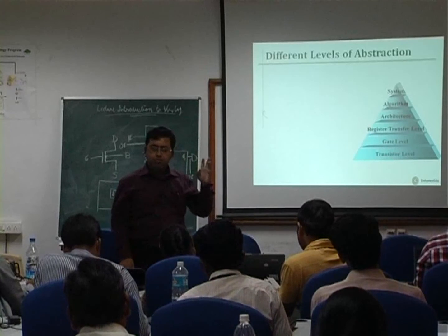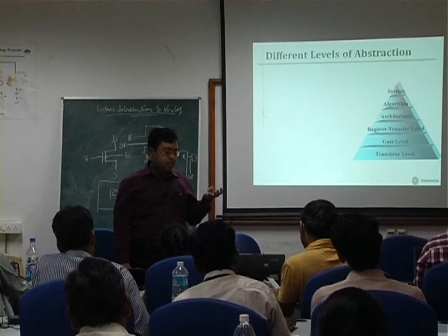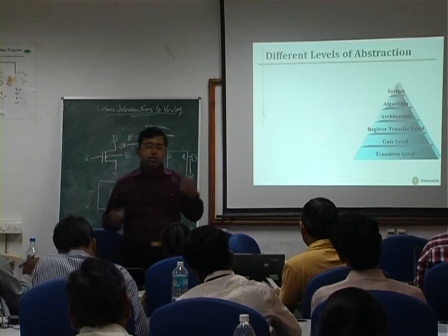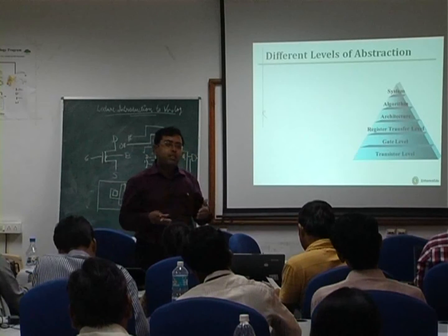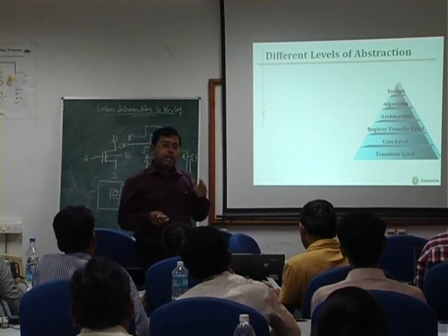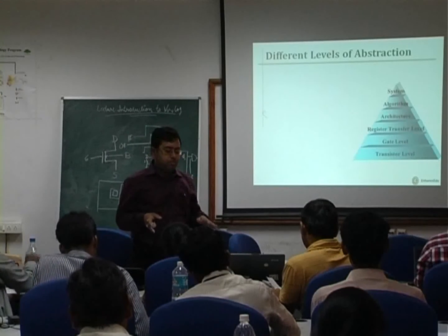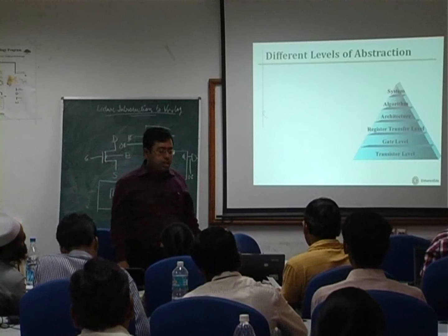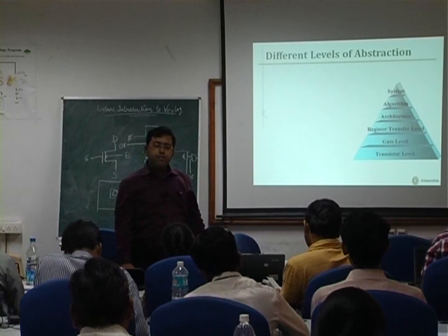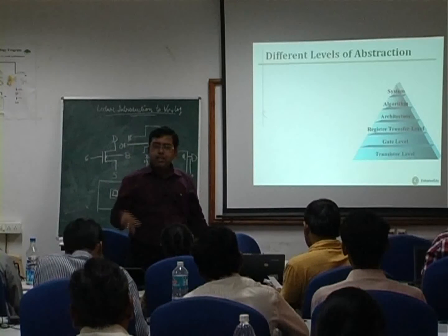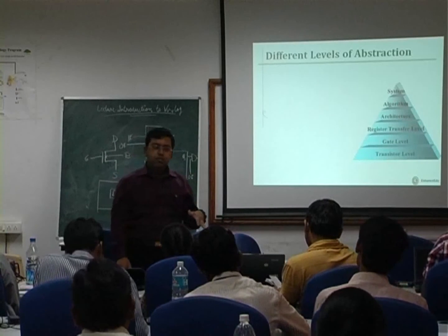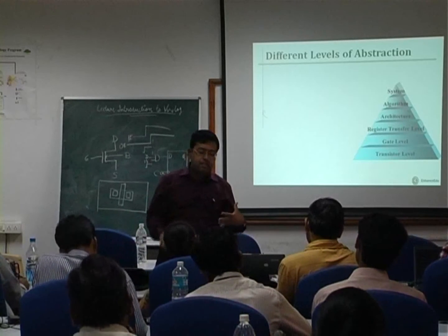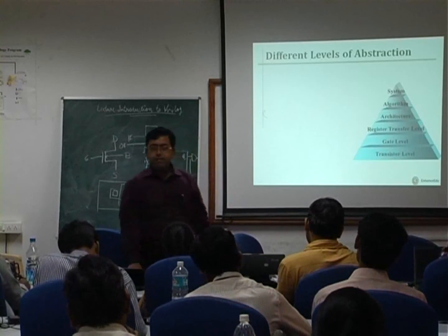We are only bothered about the behavior of the circuit, and then translate our notion into an algorithm depicting accurately the behavior of the system. And gradually this algorithm is translated into the architecture of the circuit, and after that the architecture is translated into the data transfer between the registers, which means we exist at the RT level or register transfer level.